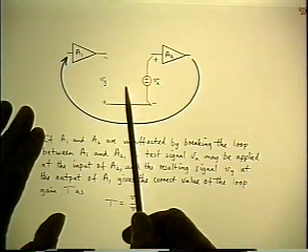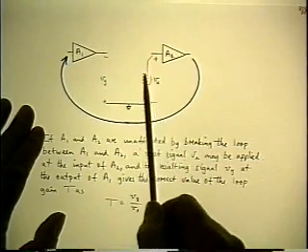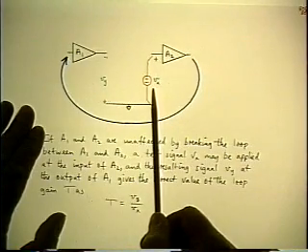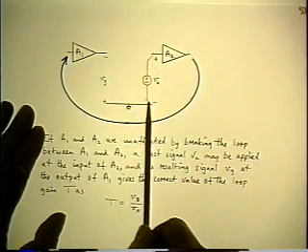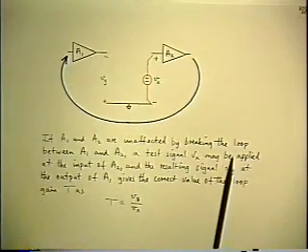So we're certainly going to want to make a measurement of it directly on the breadboard when we get to that stage in the design. And you can implement this technique directly on the breadboard. You can break the loop, and you can apply an AC test signal and measure what comes out the other end. But there's one step you have to do in between.